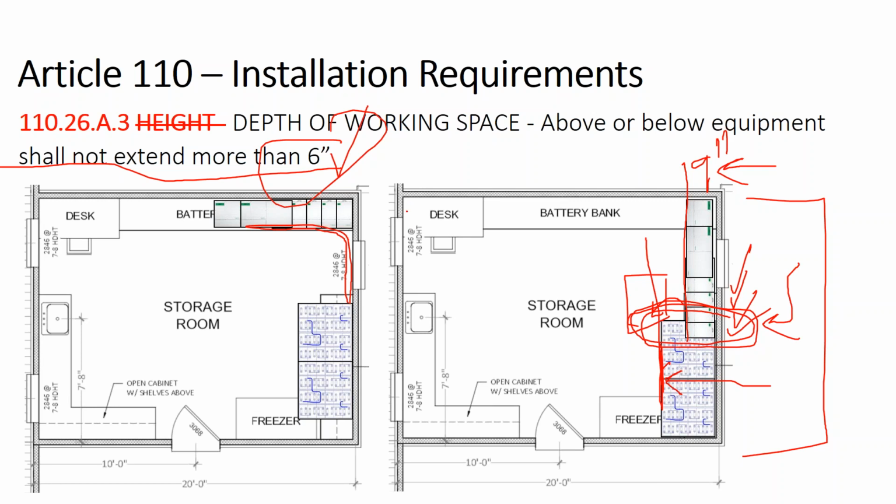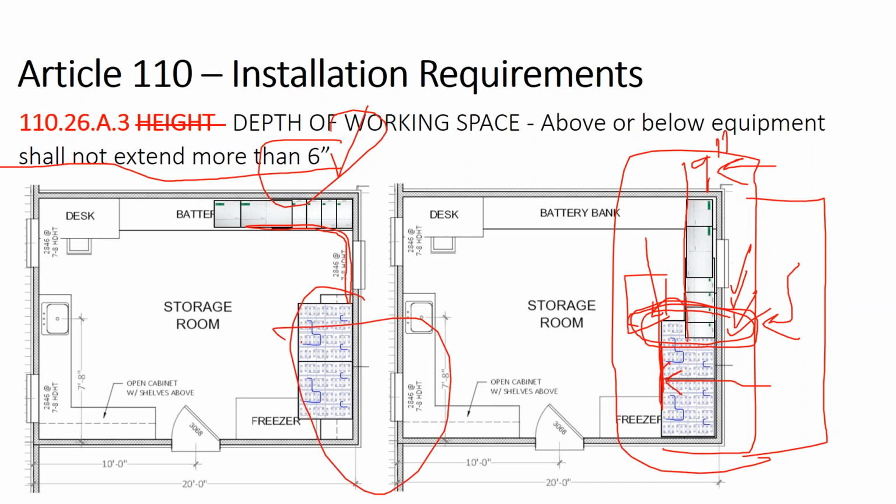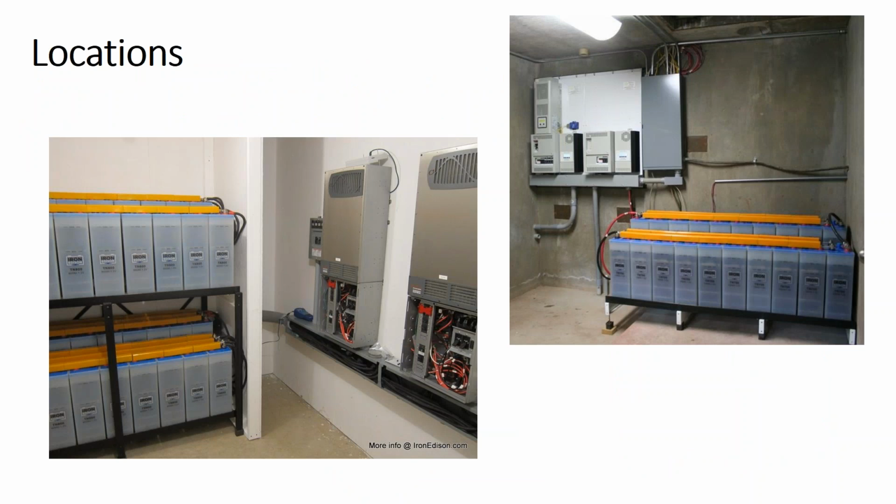Really, with this inverter wall, originally the architect had said, well, we're going to have the batteries here and then the batteries here and the inverters here. Getting further into the design, we said, well, these have to be much closer together. And that might be a reason to do AC coupling as well, so that you can have your solar inverter on one side of the facility and your battery inverter with the batteries on another side of the facility. Sometimes your design constraints are going to make it so that DC coupling is not possible.